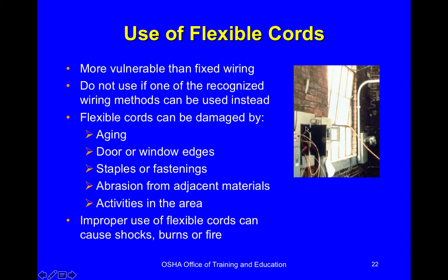Also an issue here with this electrical panel, it's open, it's outside, it looks like, it's open to the weather, and you have wiring hanging out. Okay, that means that the protective cover on the inside is not there, so somebody could just touch that and probably have a severe burn or electrocution.